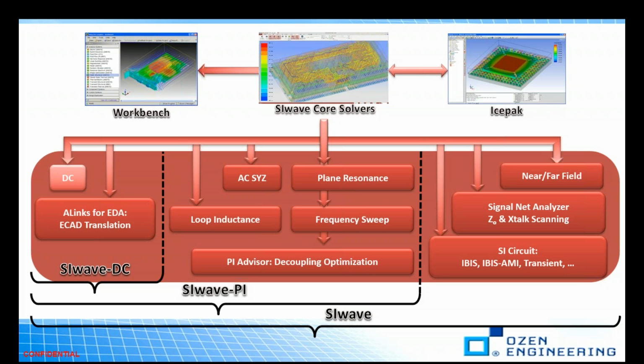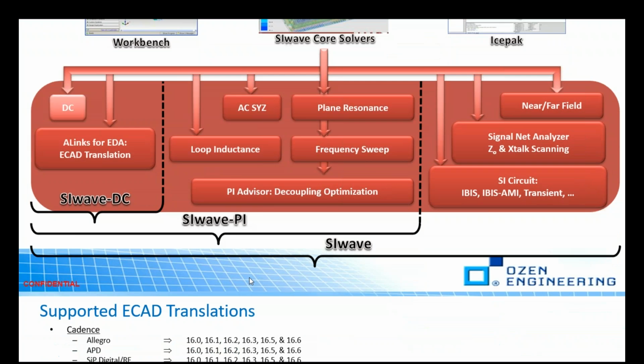So by doing so, the closed loop calculation, this SIWave coupling with IcePak, can give you useful insight into the thermal behavior of key PCB sections.